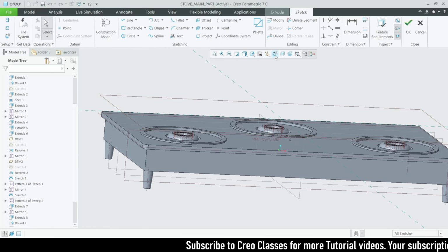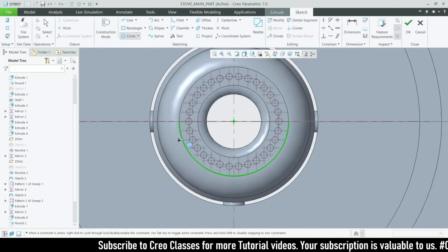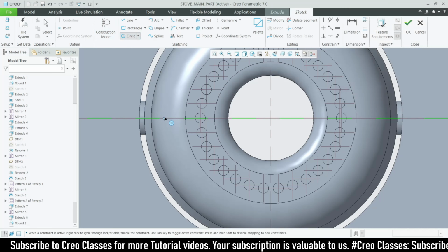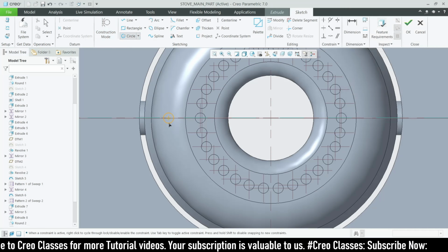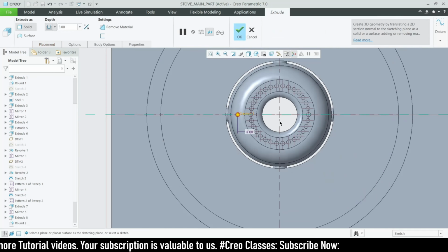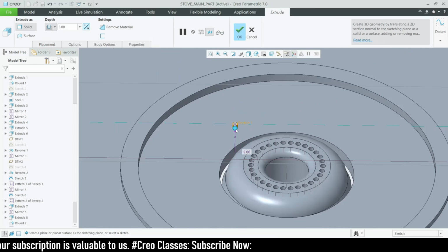And let's go for the extrude on the new plane. Let's go for the sketch view. So here I'm just going to draw a circle in this reference itself, okay, like this. And this will be the same as 3, and the extrude length will be different, right? So let's drag it like this.